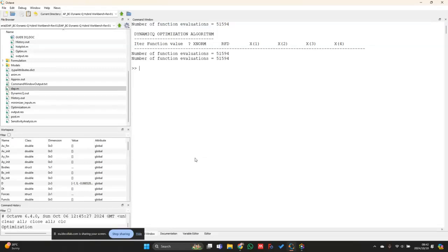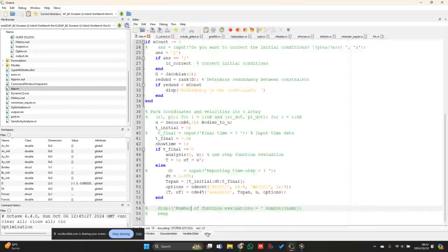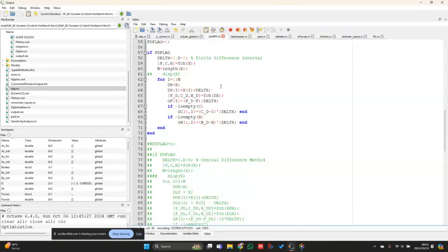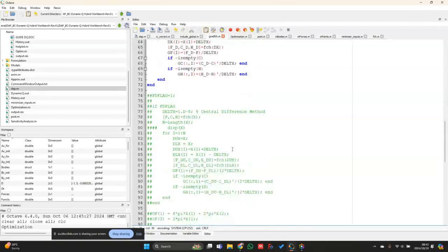So it does calculate, because you specify, I think if we go back to grad FCH as well, so it's not going to calculate between 2 consecutive design variables that it chose. It's just going to calculate at the initial design variable that you specify, and then it's going to take a plus 1 times 10 to the power of minus 8 step to the right, and then it's going to calculate the gradient over there. And that basically guides it from a localized perspective in which direction it needs to move for iteration 1 and iteration 2 and so forth. Yeah. But with regards to the results that it runs, yes.